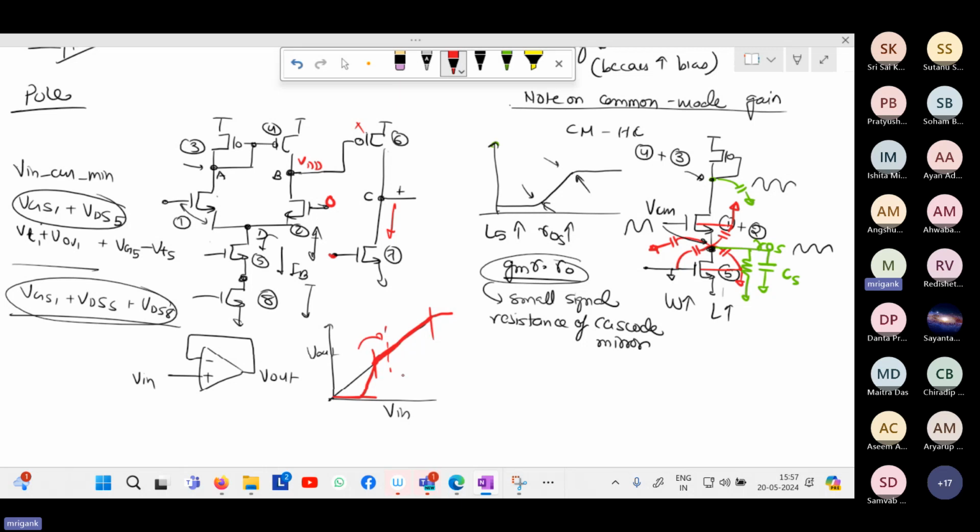For differential operation in a feedback loop, we would like the amplifier to be able to handle the common mode signal, so the input common mode range should be good. In the feedback loop, whatever the DC level of the signal, it should be able to operate, because the DC level can be any value. So in order to have full range, we should be able to deal with the entire DC range, especially for a voltage follower where the signal can have any value. If the signal is known to have a very small value, then you don't need to worry. So that is where input common mode range needs to be checked.